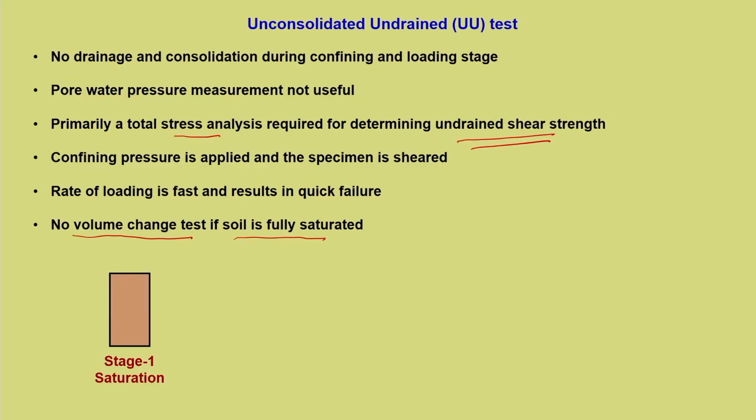So, the same thing is applicable here. If there is air present in the sample, then air will get displaced in the process. So, what is going to happen is, if it is fully saturated, whatever is the initial effective stress, that remains the same. But if you allow any sort of volume change, that will alter the initial effective stress, and once it is altered, the strength also gets affected. So, that is the reason. So, it is understood that no volume change takes place.